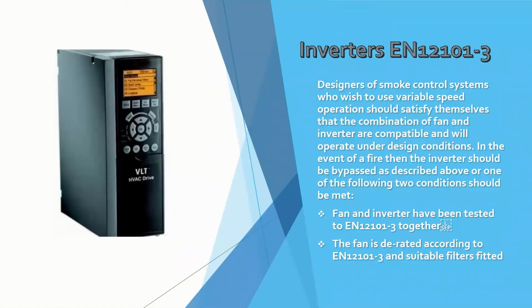At times, a fan manufacturer may recommend the fitting of a specified inverter to control the fan speed for better motor speed control. Only the fan manufacturer's recommended inverter should be used, as these will have been independently tested together to ensure compliance to the system it was designed for, and tested together to the relevant EN standard with the relevant CE mark and declaration of performance.